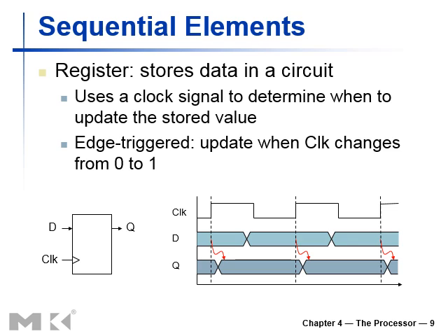Now coming to the sequential elements, we use registers in order to store data in the circuit. Registers are the sequential components that are synchronized with the clock. Either we have synchronization with the positive edge of the clock, or with the negative edge of the clock. If you see this timing diagram here, the system is synchronized with the positive edge, and whatsoever the value of D is on a positive edge, that has been latched to the output on the positive edge only.